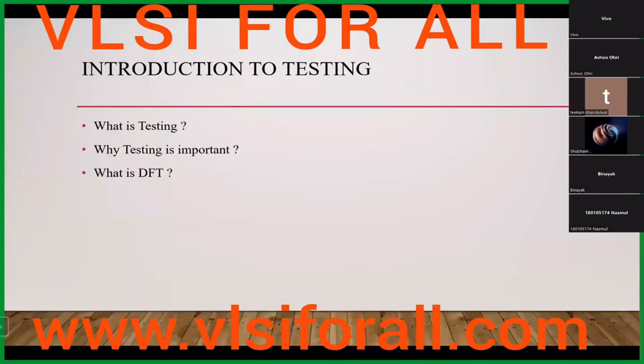To reduce the number of patterns, I'll explain the patterns and other things as we go further in this. But yes, to reduce the number of patterns and to reduce the time taken to test the circuit in VLSI, that is the definition of DFT. So you have already answered that question, why we call it DFT, because we are designing some part of it for testing only.